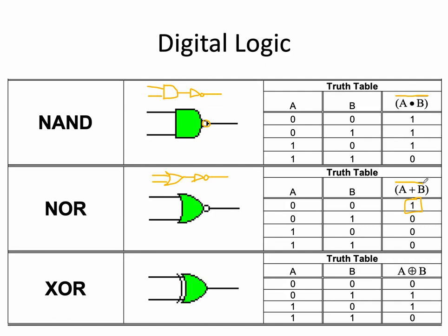Exclusive OR is a little bit more interesting, and this is one circuit we've never talked about before. Sorry, for all the inputs here, A and B are over here. XOR, exclusive OR, is what XOR stands for. And exclusive OR's output is true only if A is true or B is true, but not if both of them are true.